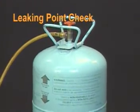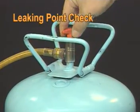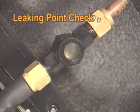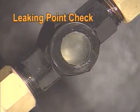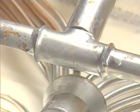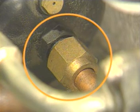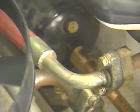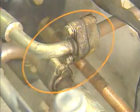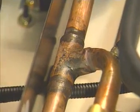When the refrigerant lacks after driving for a long time, refill the refrigerant and drive because there's a tiny leak in the system. However, if the refrigerant lacks again soon, find the leaking point for repair because it means a serious refrigerant leak. Since the serious leaking points are polluted with refrigerant and lubricant oil, it can be easily found by eye check. As for the leakage check, check the fitting and welding points first.